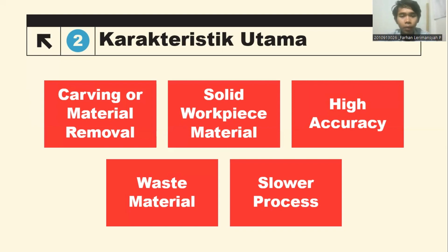So, subtractive rapid prototyping is often used for prototyping that requires a high level of accuracy or for producing smaller components with harder material. It can also be used to create objects from material that is difficult to print using additive rapid prototyping methods. However, it's important to note that using solid materials and the machining process can be time-consuming and require expensive CNC equipment.